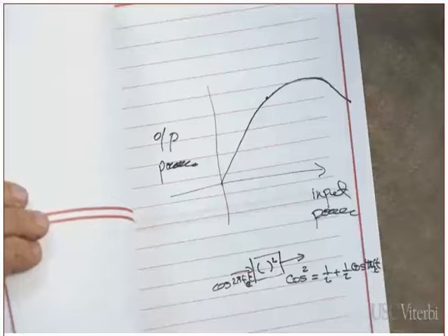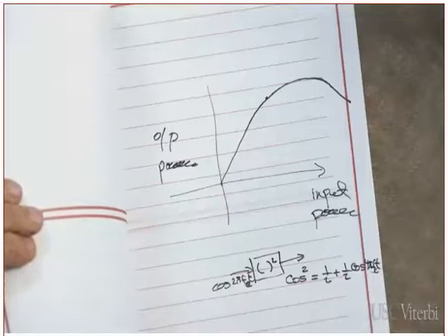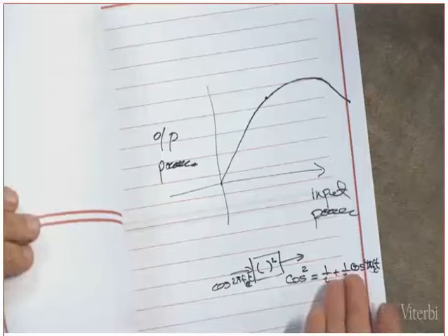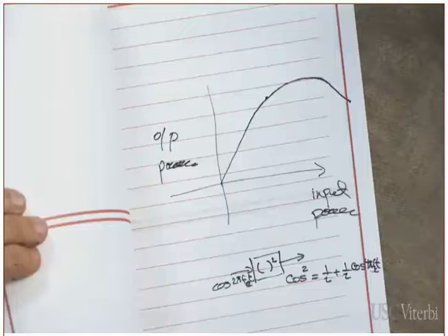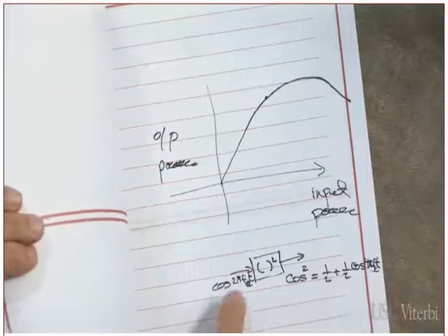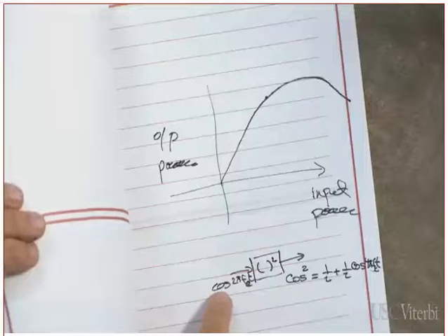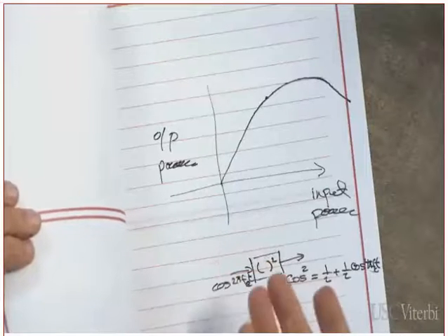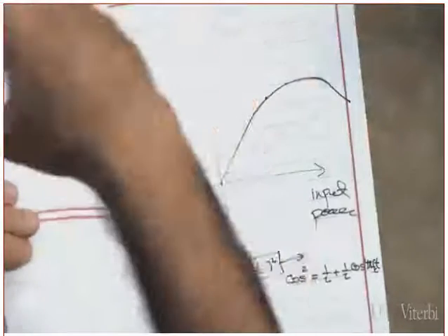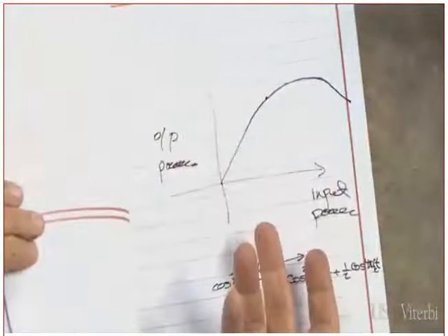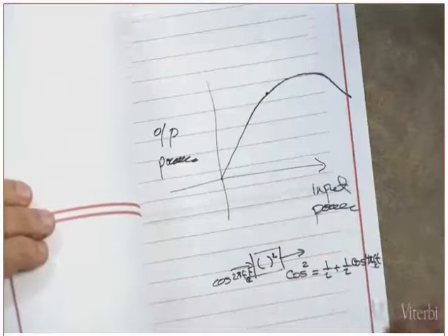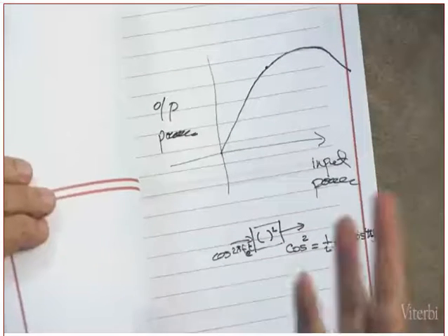Could that second harmonic interfere with other devices, with other transmitters operating at that other frequency? That's what I meant by generating all of these side lobes and stuff. You might say, Professor, but this is just the second harmonic. It's not a side lobe. But you have to remember, the input to the square law device is not a pure carrier. This is a pure carrier. In reality, the input to the amplifier, to the nonlinear device, is a carrier modulated by the information. Yes or no? Are you following me, or are you losing me? You are not transmitting only one carrier signal with no information.